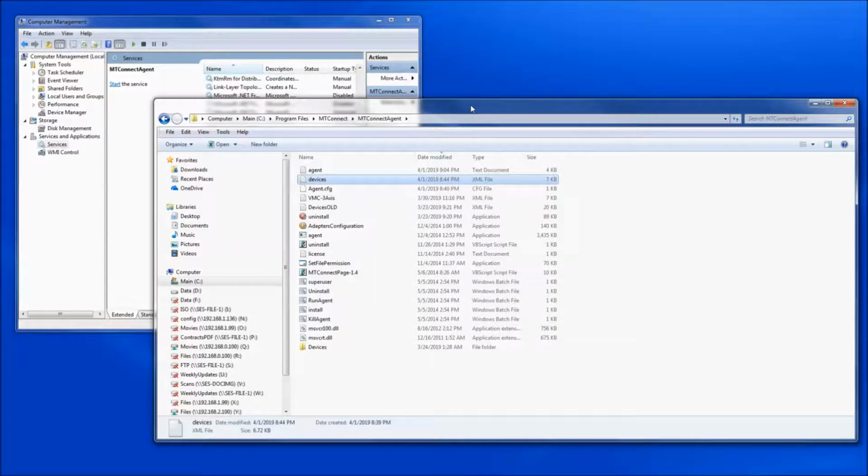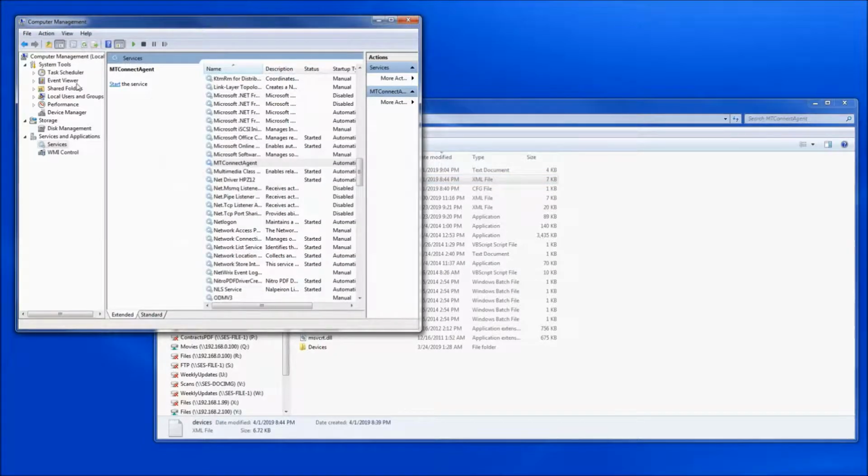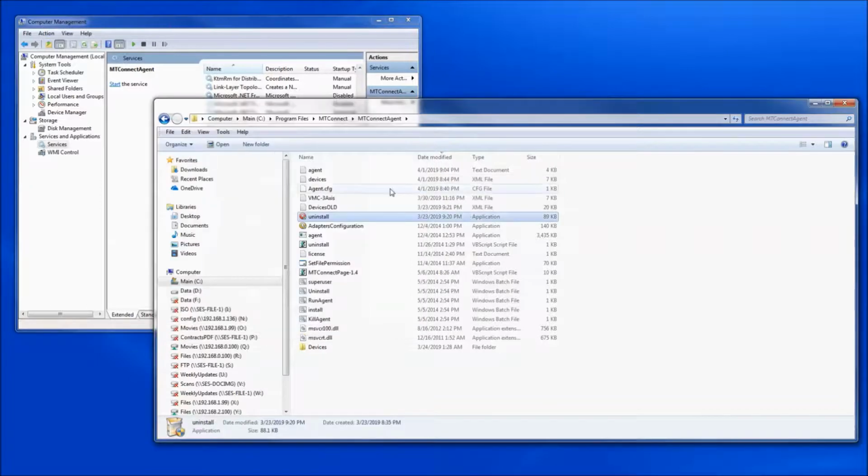We're going to take that adapter that we made and connect it to internal data of the PLC, and we are going to connect it to the demonstration agent that's supplied by MTConnect. And I went ahead and installed that. It can either install and run as a service. You can see I have the MTConnect service here. I just started using this for testing where I can stop and start this here. But it works out of the agent directory, which is in Program Files, MTConnect, MTConnect agent, is where it installed itself.